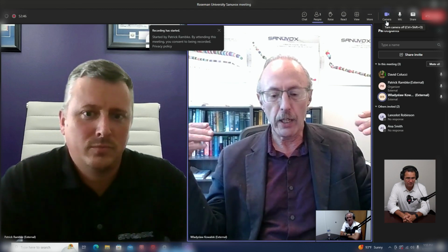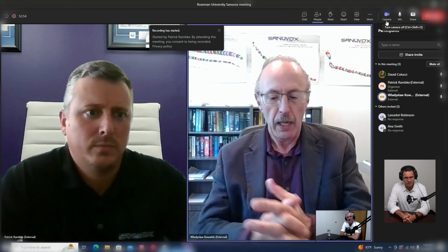The intense UV radiation can only exist in the upper zone. And therefore, these units typically have grills on the front. They try to force the light to be parallel so that you get parallel beams of light going across the room and not straying down into the occupied zone. That's basically what the grills are for. They try to concentrate all UV in the upper zone, and that's where the UV is operating to clean the air.